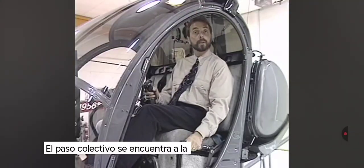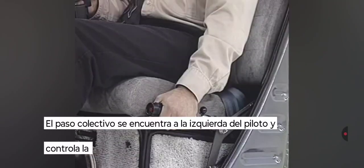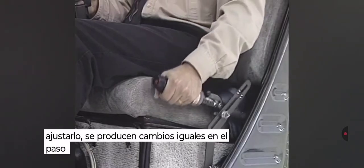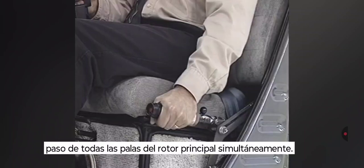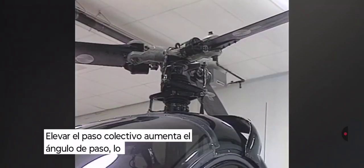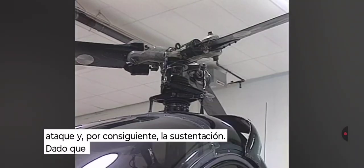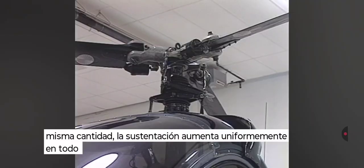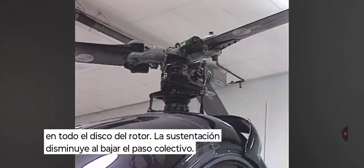The collective is located on the pilot's left side. The collective controls altitude. Adjusting it makes equal changes in the pitch of all the main rotor blades at the same time, or collectively. Raising the collective increases the pitch angle, which increases angle of attack, which of course increases lift. And since all blades are increased in equal amount, lift is increased equally across the entire rotor disc. Lift is decreased when the collective is lowered.